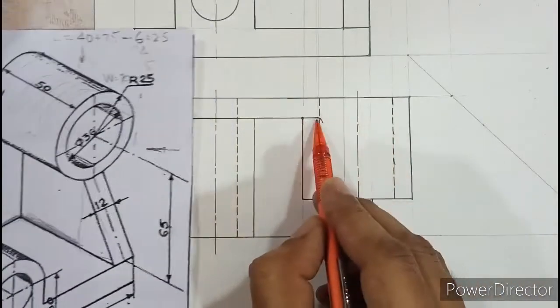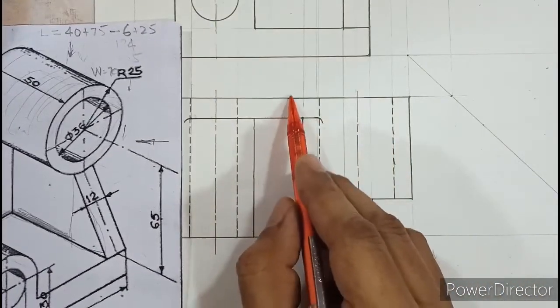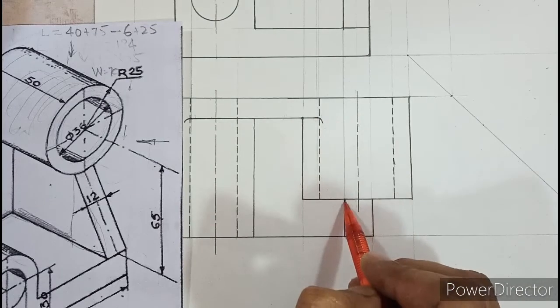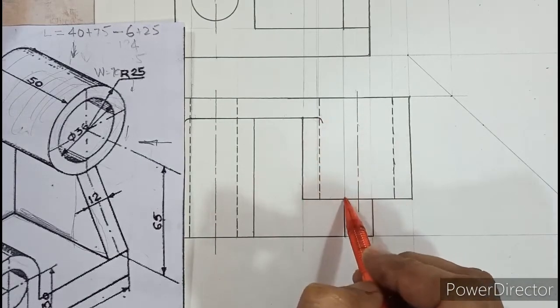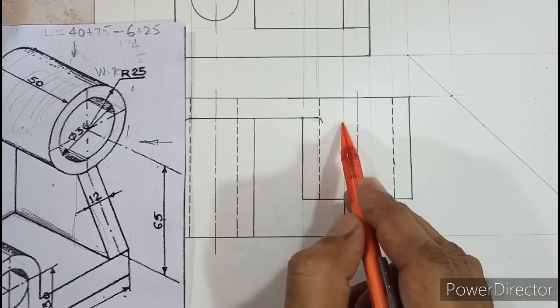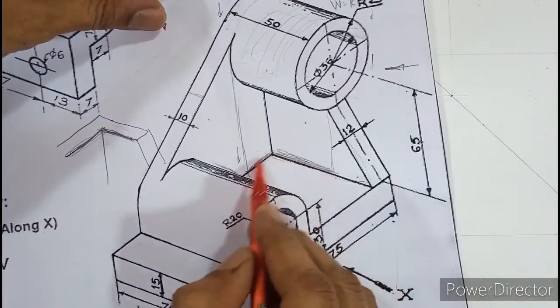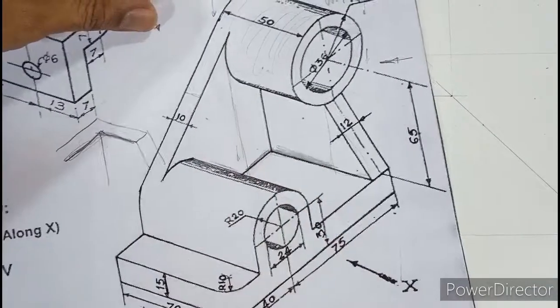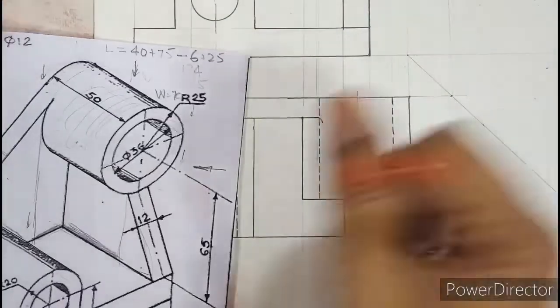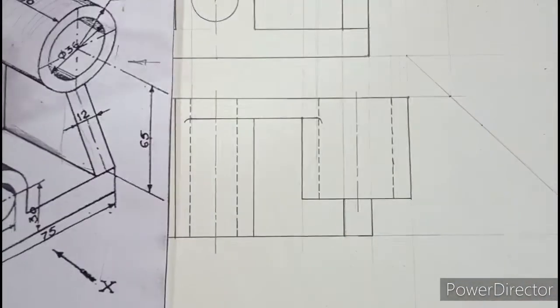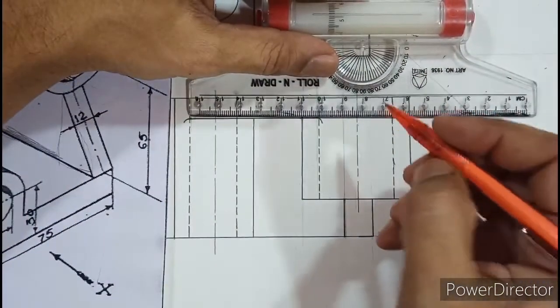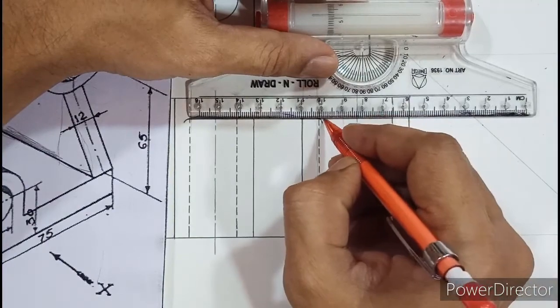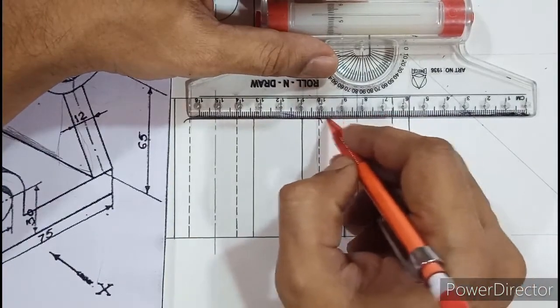See, 10 from behind means this rib is 10, isn't it? So if I extend this here, you need to draw hidden line till here and then take an L-shaped turn. So this hidden line represents this L-shaped part. Okay, so you are supposed to show by pencil. What I am doing is I am showing by separate pen so that you can understand it. But remember, all of you have to show by pencil itself. So let me extend this 10 millimeter first.